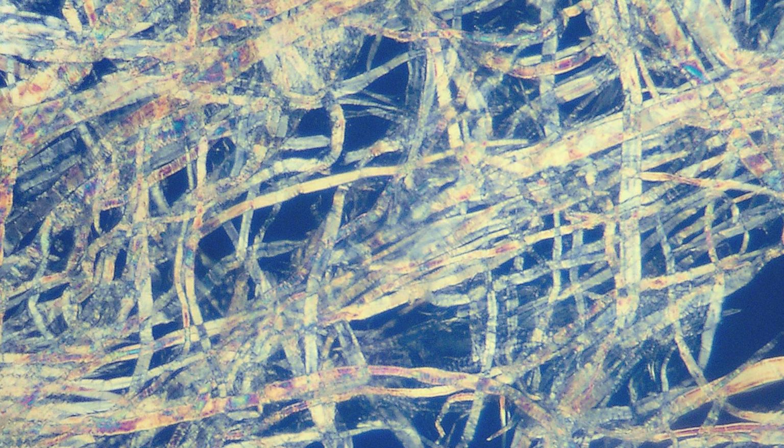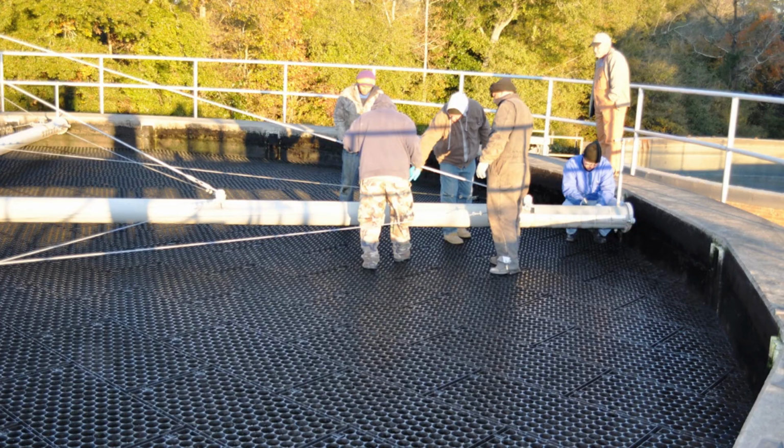Enzymatic pitch control helps to reduce pitch-related problems to a satisfactory level. It reduces defects on paper web as well as the frequency of cleaning pitch deposits in the paper machine. At the same time, it also offers other advantages, such as eco-friendly and non-toxic technology, improved pulp and paper quality, reduction in bleaching chemical consumption, reduction of effluent load, and space and cost saving in a mill wood yard by using unseasoned logs.